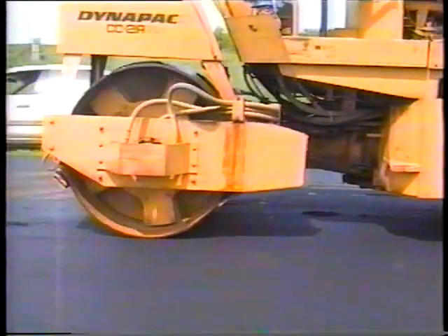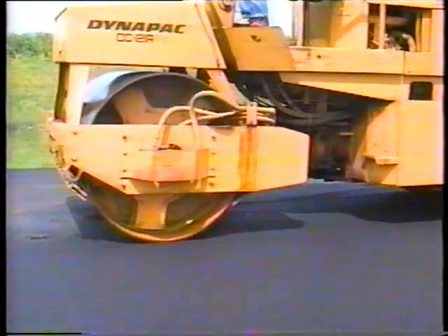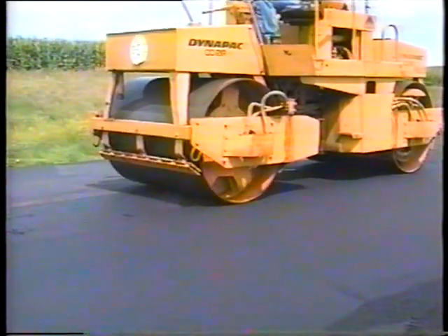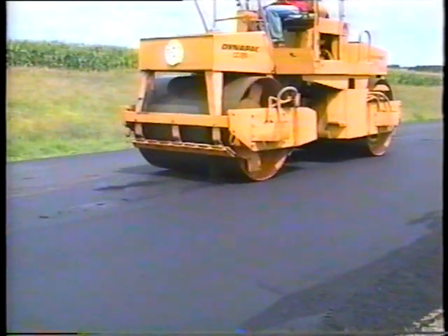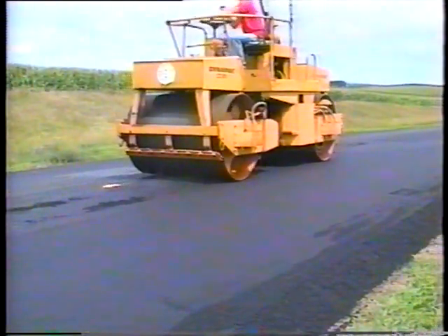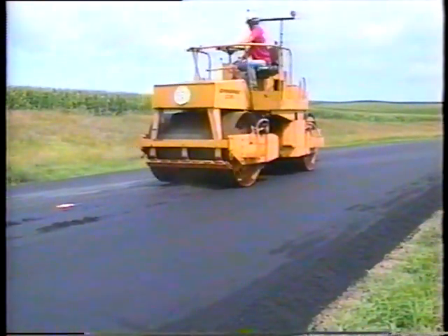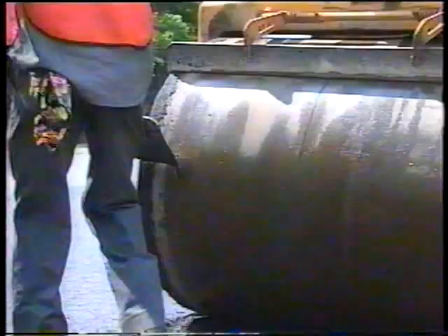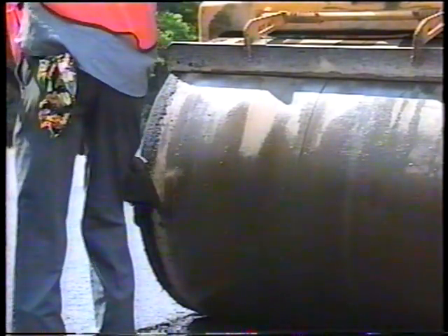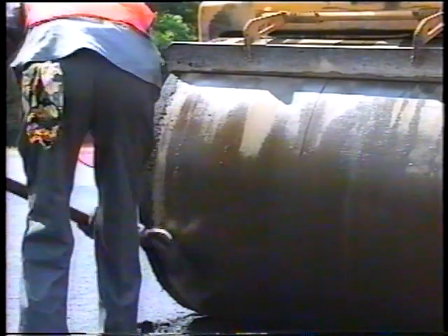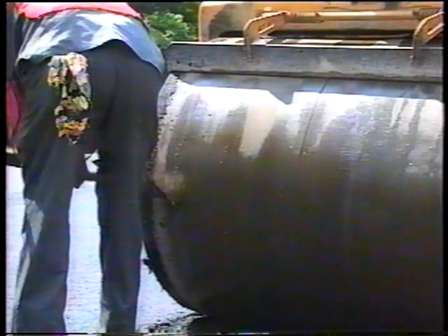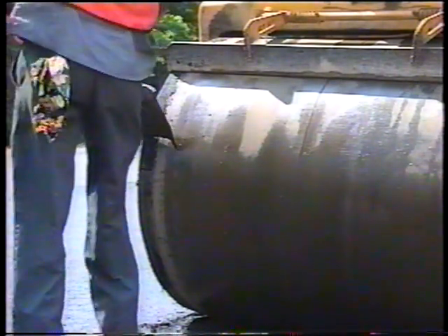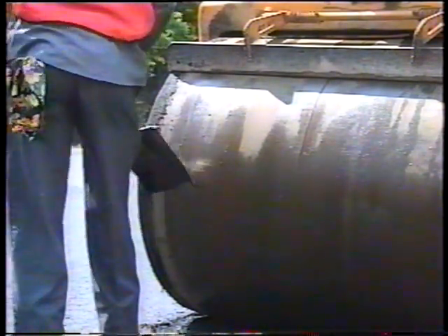And for either type of roller, the scrapers and water nozzles must be working properly. Otherwise, they'll pick up mix, a surface defect in itself, which ends up leaving impressions each time the clod of stuck mix impacts the surface. To add insult to injury, you'll end up trying to scrape hardened mix off the roller. A difficult task. And don't even think about using diesel fuel to make it easier. Remember, if it dissolves the mix on the roller, it will dissolve the mix in the mat.